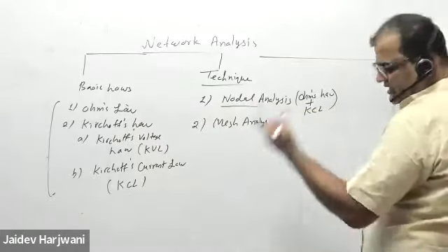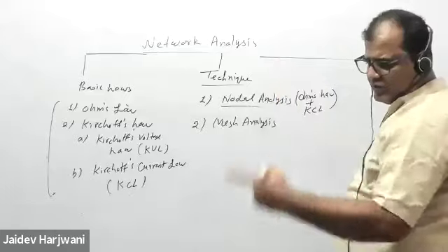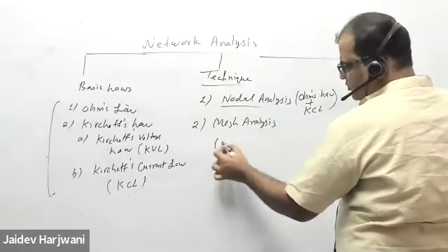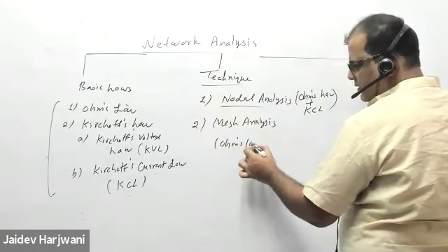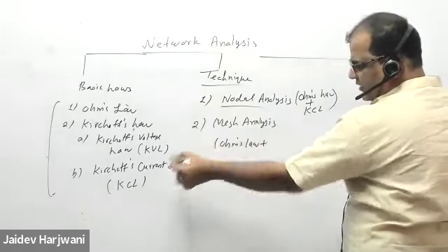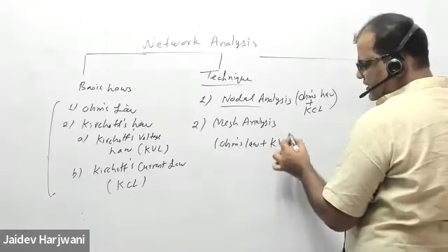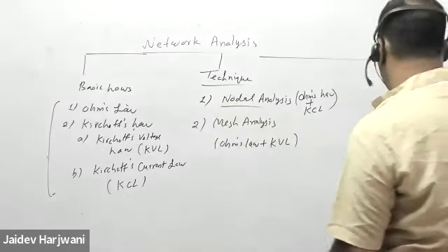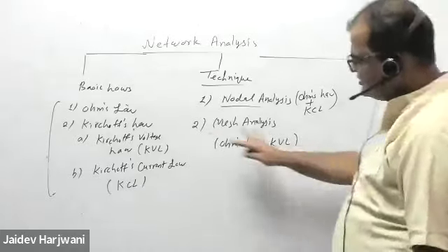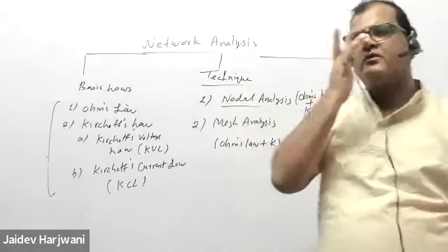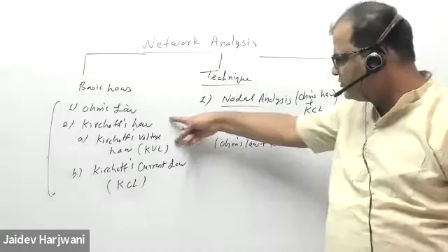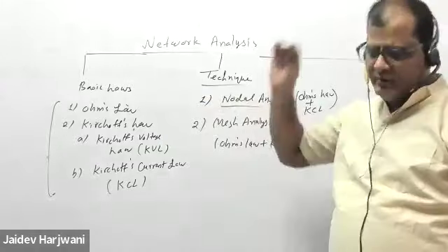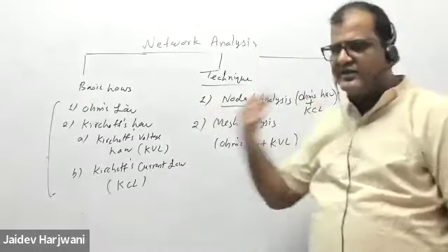And in mesh analysis, you apply voltages in the loop. So if you use Ohm's law along with KVL, Kirchhoff's voltage law, that together forms mesh analysis. These techniques are sufficient to solve any circuit. If you understand these three laws and you know these techniques, you can, in principle, solve any circuit.